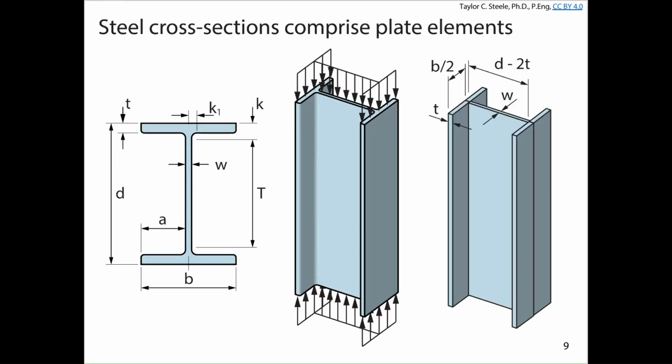So the first thing we need to do is actually evaluate what local buckling is, because it's perhaps simpler to think about what it looks like in terms of the pictures and videos that I've showed you before. But we need to be able to quantify these things. It's not just important that we can describe them, but we have to quantify them too. Basically what we've got is if we have a relatively short column and it's under relatively uniform stress from the compressive, so we've got an axial force acting on this column, what we're going to do is divide up this cross-section into the equivalent plates.